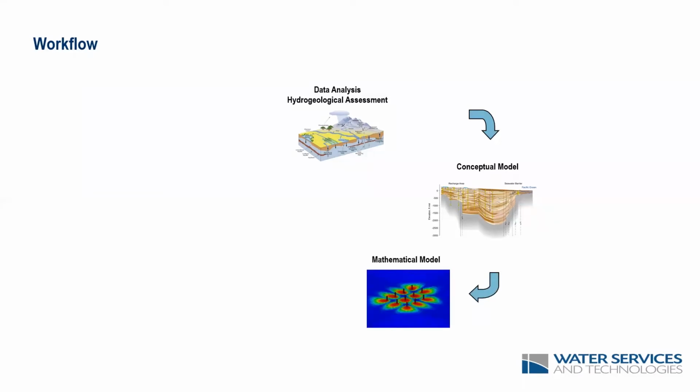And at that stage, when we are reasonably confident that we understand that natural system conceptually, then we can start thinking about generating a numerical model and start working on that model in terms of calibration before we can do any projections. Depending on what we are looking at, in this example a well field, we are thinking in terms of abstraction rates and spacing between wells.